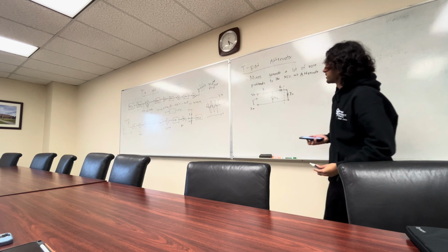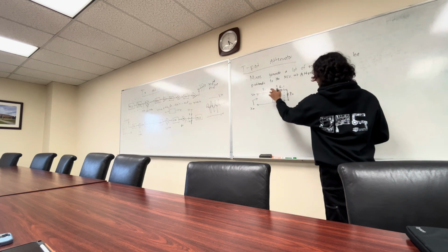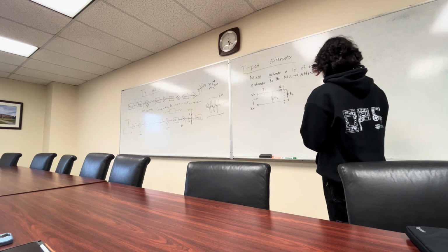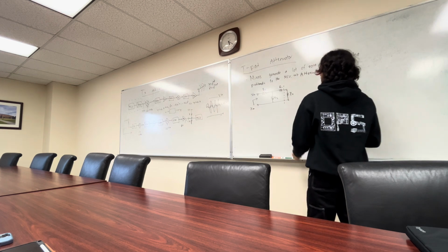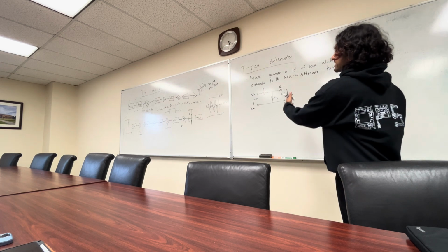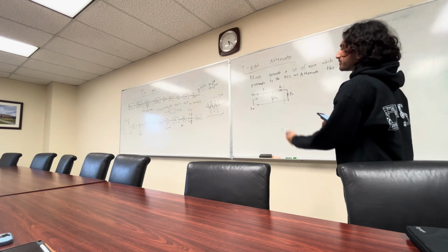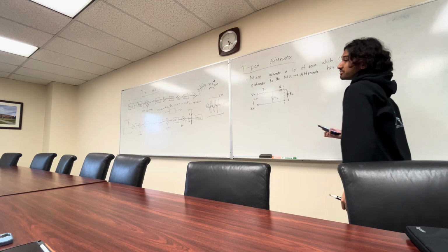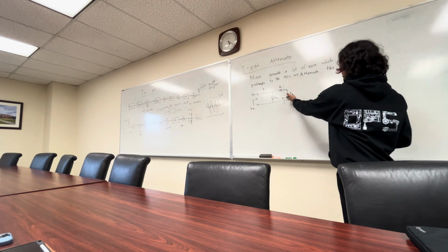So our t-pad attenuator looks like, you can tell it's a T, hence the name. And let's try and figure out the termination. Let's say we put this t-pad attenuator before a filter. The filter ideally looks like 50 ohms, and it expects 50 ohms. So that's some termination.